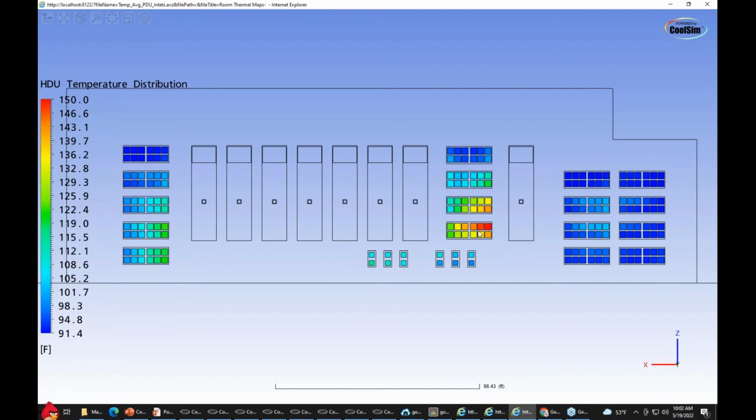I could see path lines coming into these. These are getting contaminated. The inlet temps on the heat exchangers over in this range are quite high. They're probably recirculating on themselves as well due to the pressure gradient caused by the Bernoulli effect, the wind. And so I've got problems right here in this design. So right away we say, okay, what can we do to affect that? Can we move them over here? Would it help? And you begin to play what-if scenarios.